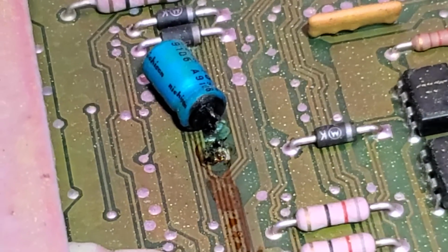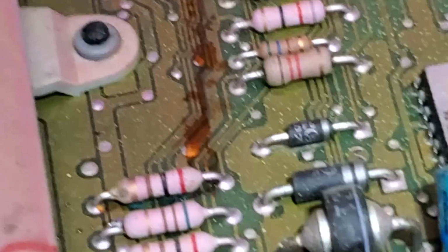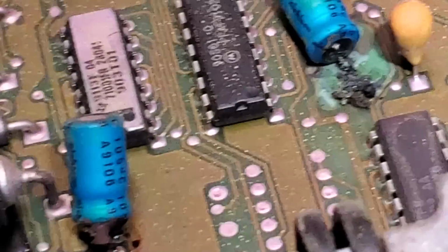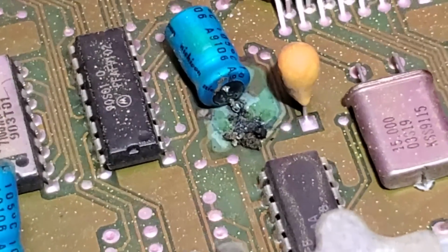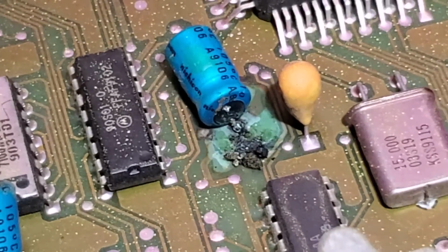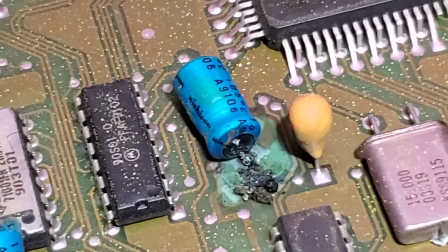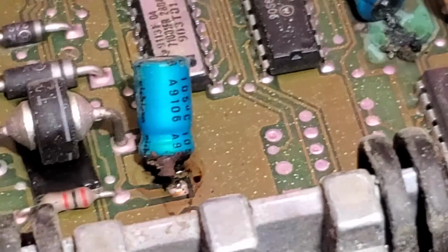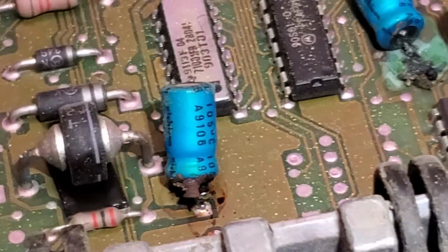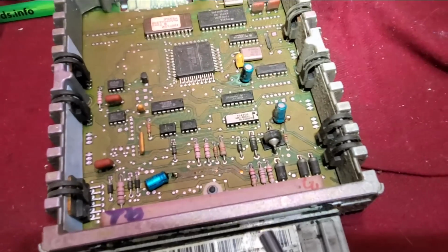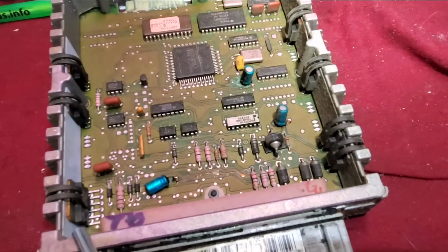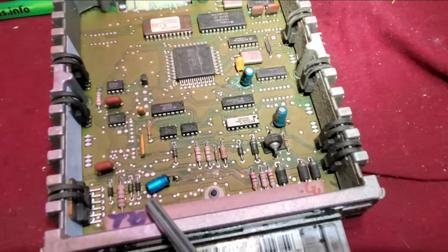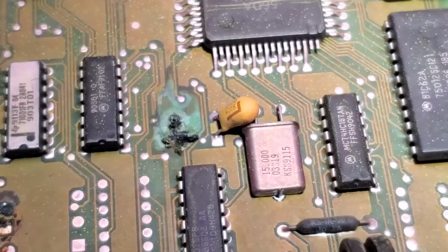Yeah, this one's really bad. The symptom or complaint on this truck was that occasionally it wouldn't start. Look at the date code, 9106, Nichicon. Clean up in aisle 5. All the negatives are on this side. 10 at 63, 47 at 16, 47 at 16.